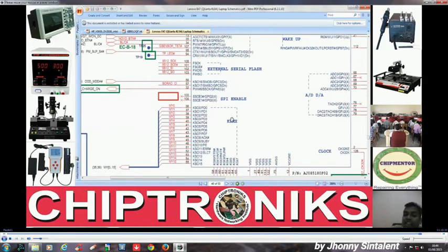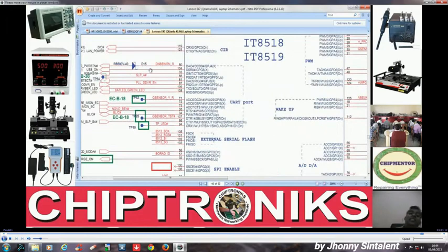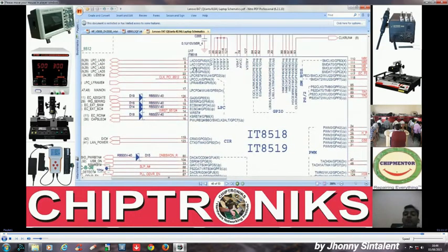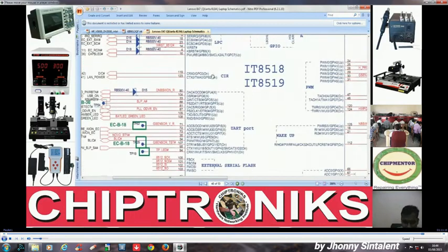But here in this case, the data is all processed inside here, right? We press the pin and a scan in and a scan out are sent. These are processed by the internal keyboard encoder, sent to the internal keyboard controller, and then sent to the processor via these four pins. But how does this data transfer take place?